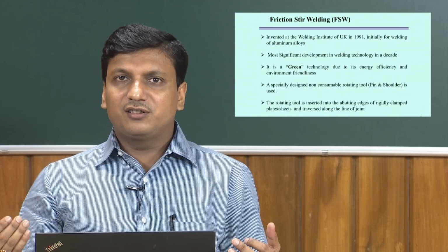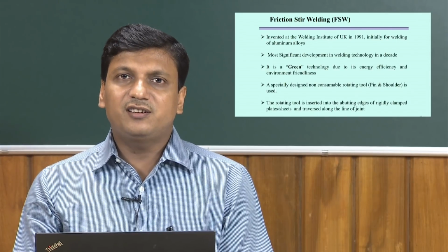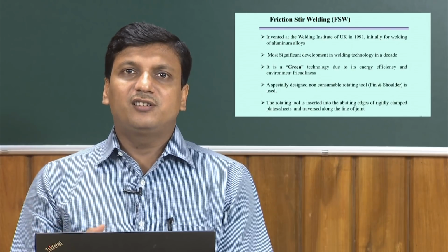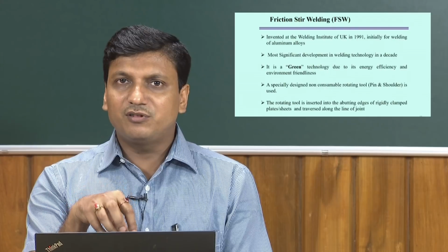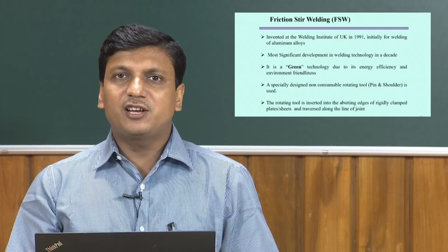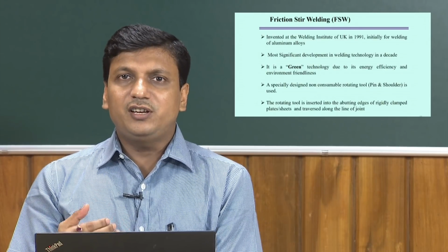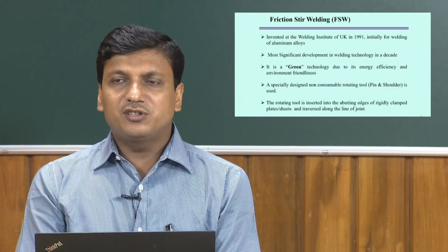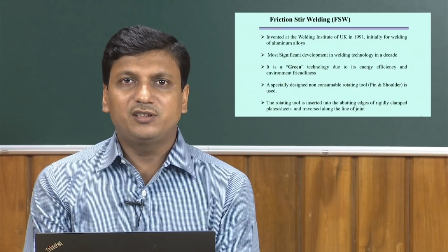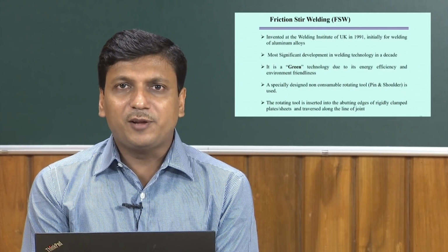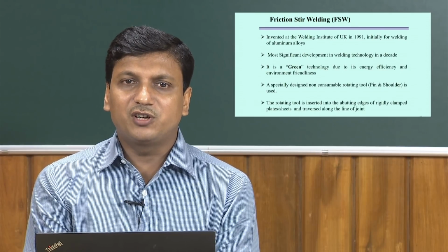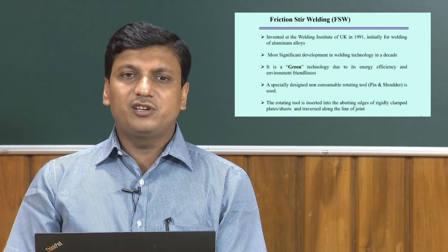That generates the heat, and that heat plasticizes the material around a very defined, very small zone, and then after plastic stirring the materials can be joined. Similar kinds of materials as well as dissimilar materials can be joined by this process, but at the same time the maximum temperature within the system will never cross the melting point temperature. So, it is a kind of solid state welding process.